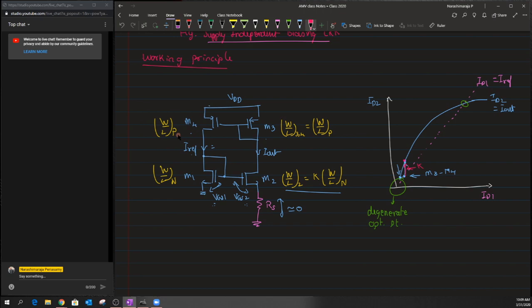Okay, and this new current, which is my I out current, is then again copied onto this M4 M3 combination structure, and it results in this I reference current. So again we need the help of this M3 and M4. This kind of combination works in such a way that the current through this M1 M4 combination will always be larger than the current through this particular path.